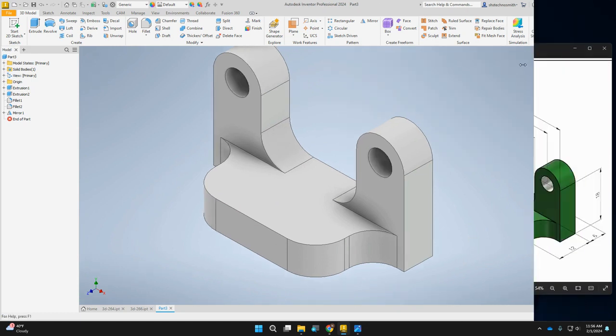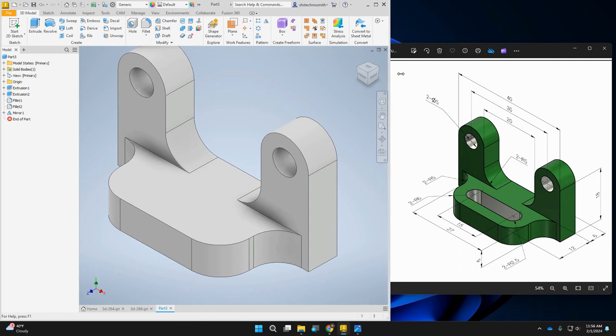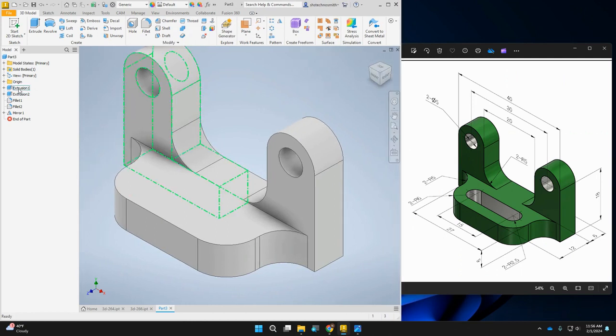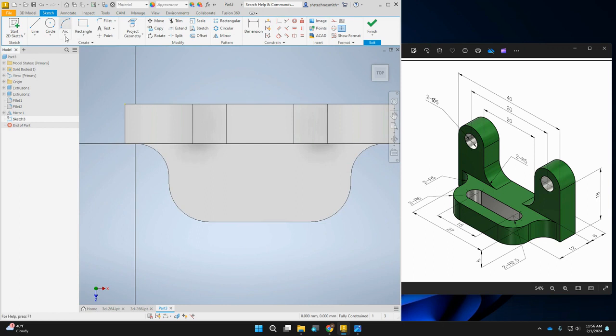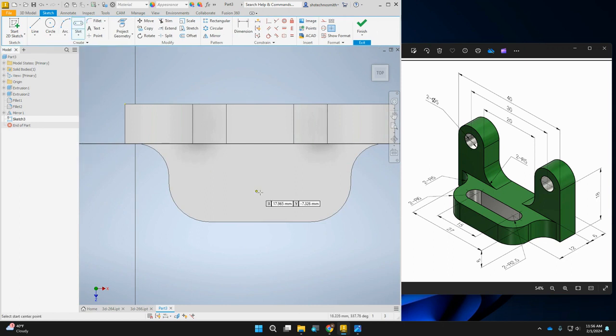All right. So we've got those 2 sides. So that's kind of nice. If we want to go back and make any changes, we can make changes to one side. We don't have to then make changes to the other, and our mirror will always work. So then I'm just going to finish this up with a slot like we did earlier. Get that center to center slot. That's the most common. We'll drop that in there.